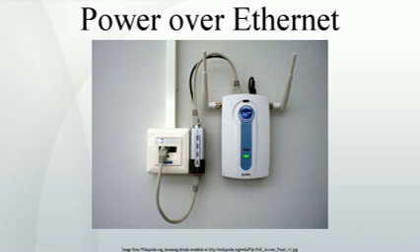When data rate and power requirements are both low, other approaches may be viable. Mobile phones, for example, use batteries for power and antennas for communication. Remote weather sensors use very low data rates, so batteries, sometimes supplemented with solar power, and custom wireless data links are used. Depending on the application, some of the advantages with PoE over other technologies may be: inexpensive cabling carries both data and power, power to equipment can be remotely cycled, fast data rate.